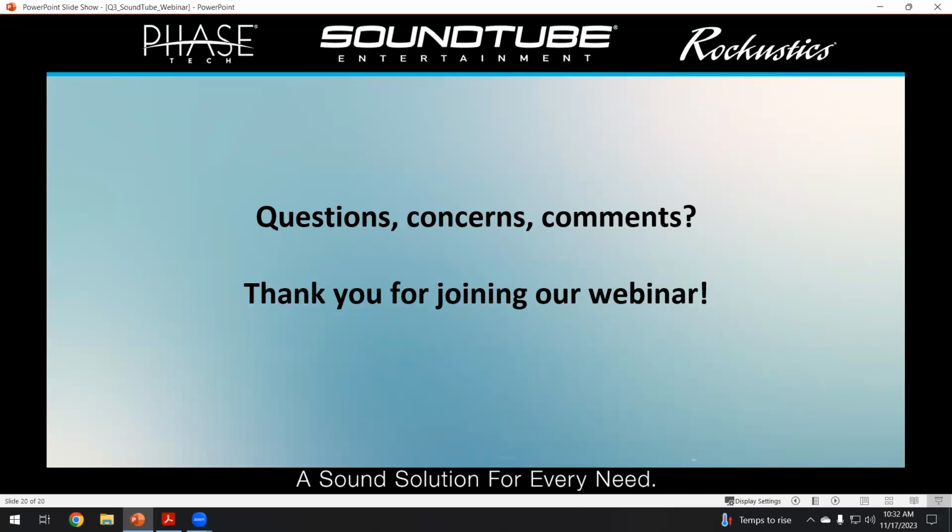That's a great question. Ken, can we do that? Yeah, so you can do that on the output gain. The output gain isn't affected by the RVC. So you can set a max limit on the output gain so that you can't turn the volume up past whatever point that you want it to be turned up to. So yeah, you can set a max limit, or theoretically a minimum limit, but you can't hone them both in separately.